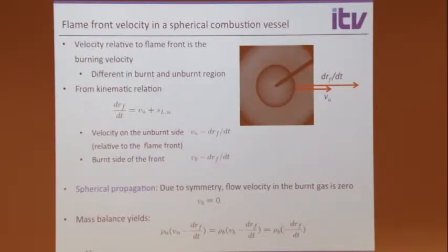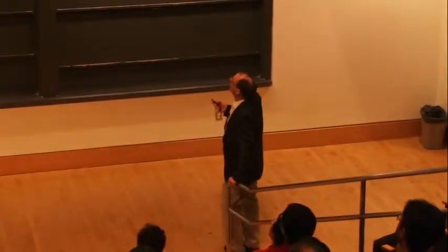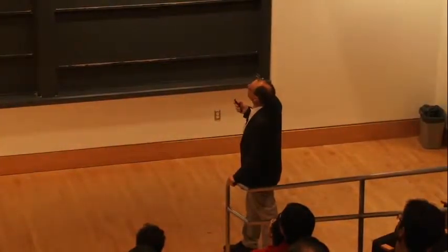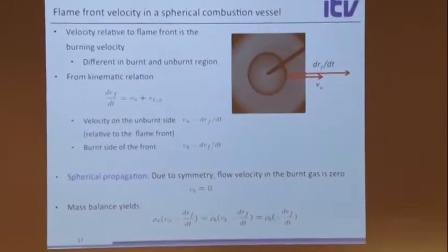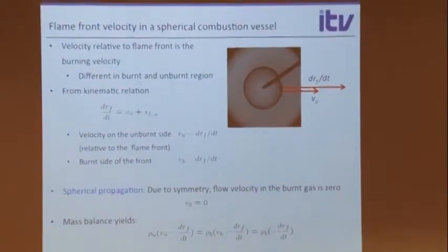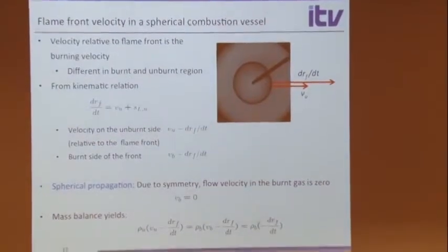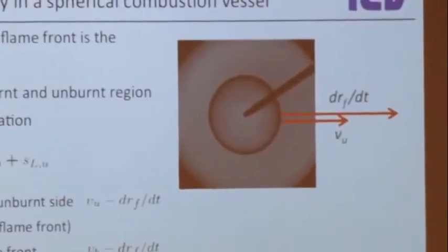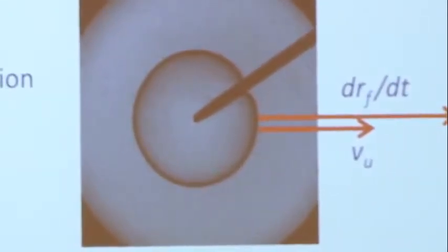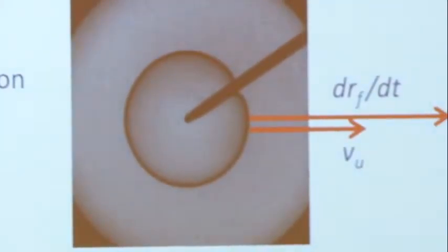Is there heat transfer going on between the electrode and the flame boundary on the lower side of the electrode? It becomes kind of non-spherical with large radii. Yeah, I think it's the heat transfer, but it's also just the no slip condition that you have. You induce a velocity, and that is just decelerated there at the electrodes. The electrodes come in like this, so they don't come from opposed sides. They come in from the side, so that you have a disturbance just here in this corner, and all the rest is not disturbed. And then you do kind of a fitting of the overall shape.